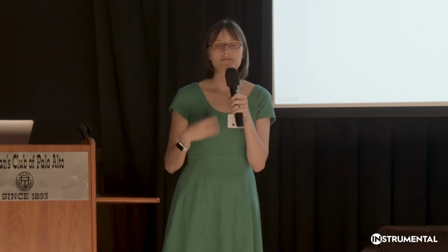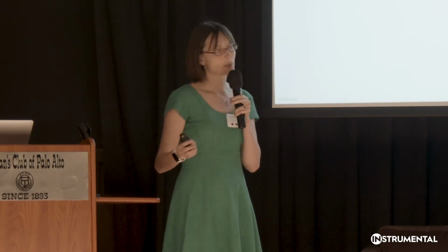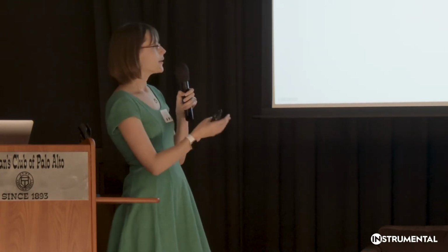So we also can reduce DOEs because there's a data record, you can actually do your DOE virtually just based on the data you already have. So you can answer your engineering question without having to build more units. That saves money, especially if you're looking at small error rates where you'd have to build large populations.